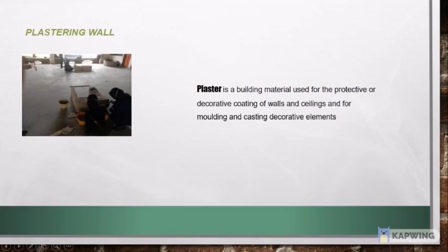Generally, the plaster thickness should not exceed 15 mm, else the mortar might fall due to its self-weight, and cracks can be initiated at a later stage. A mortar mix proportion of cement and sand at a ratio of 1 to 5 is generally used for plastering. When we do the plastering, we need to use a scraper, hot bucket, and trowels.